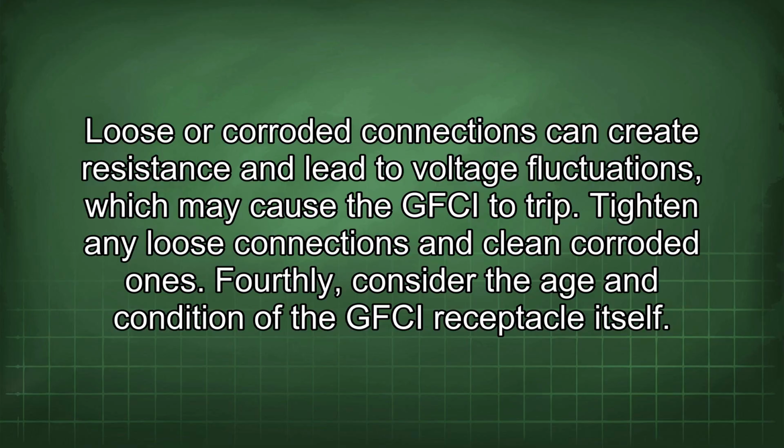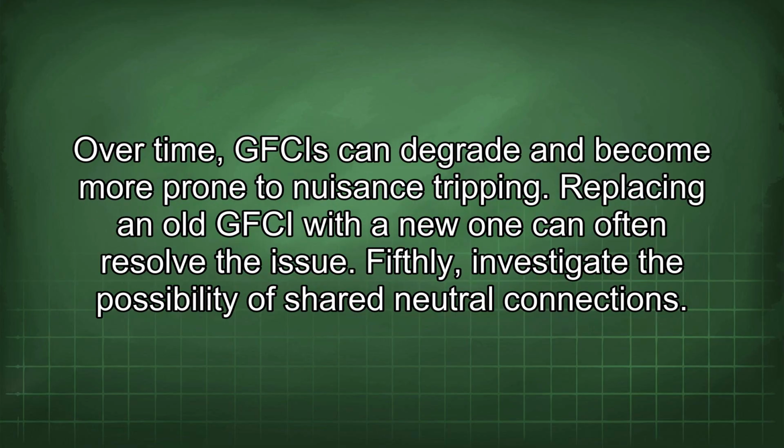Fourthly, consider the age and condition of the GFCI receptacle itself. Over time, GFCIs can degrade and become more prone to nuisance tripping. Replacing an old GFCI with a new one can often resolve the issue.